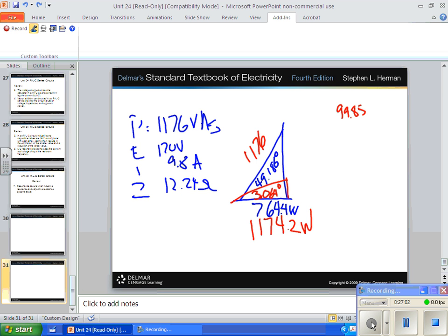What's going to happen is this motor is going to run at less than 100% when it's under what used to be full load, right? So if we only need to crank 764 watts with this new power factor corrected motor, what's it going to draw? Now, let me tell you what's going on. What happens here is we're drawing a certain amount of current, right? 9.8 amps. And if we find our new current, it might be more than 9.8. It will almost for sure be more than 9.8, because now, or will it?